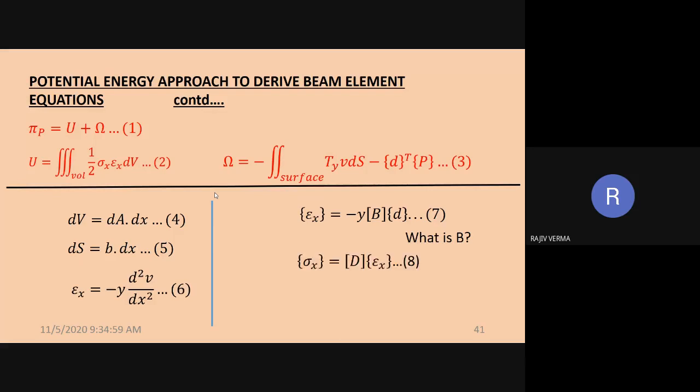And then once the strain matrix is known, you simply multiply it by the elasticity equations to get equivalent stresses. For a beam element, that is a one-dimensional case, the elasticity matrix D simply happens to be the elasticity modulus itself. It is a matrix of size 1 by 1.